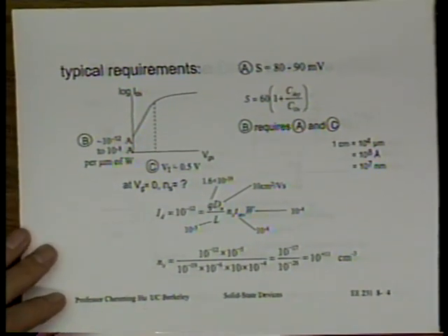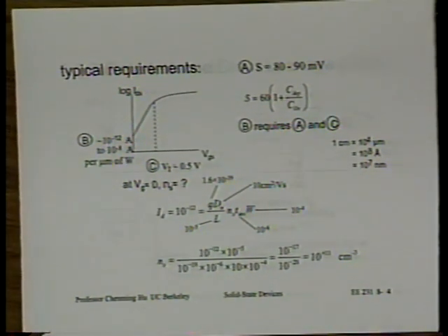All right, the typical requirement for this leakage current, how much leakage current can we tolerate? Well, that number has been changing. It used to be that we really didn't want to tolerate any leakage larger than a picoamp. Today, for many applications, we still want to hold to that. Perhaps a DRAM, because of the refresh current requirement, we don't want to lose the charge rapidly, so we want to hold the subthreshold current very low.